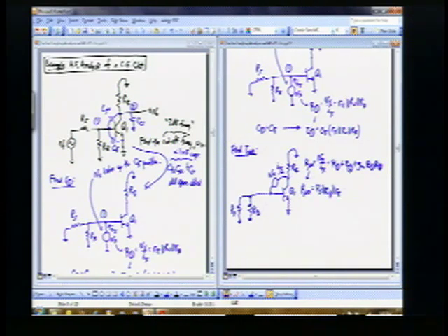And then what's this R2? All the resistance in shunt with that node. Yeah, it's RC, but to be complete, I'll do R naught in parallel with RC. But you're right, you can neglect the R naught in most cases. And then, finally, this last term is just GM times both of these terms we just wrote down. So GM times RS parallel RB parallel R pi times R naught parallel RC.